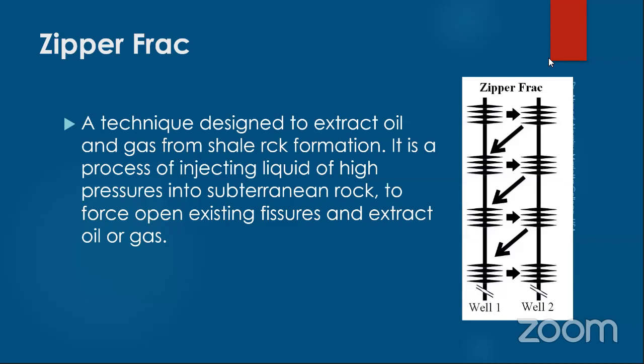Mustafa Tarek is asking, can we apply acidizing to produce from shale? Yes, sir, we can do that, but we use some acids at the beginning of the frac job, of fracking every stage, to lower the breakdown pressure. And you do this only if that shale includes a good amount of carbonate.